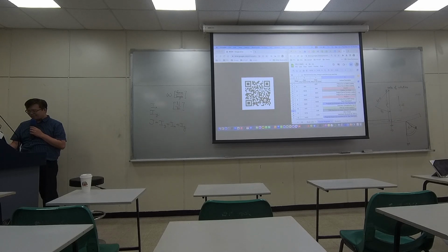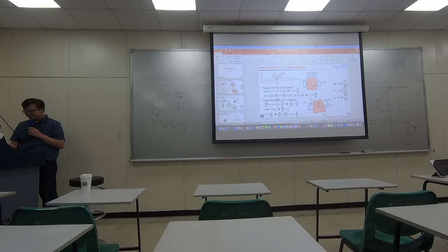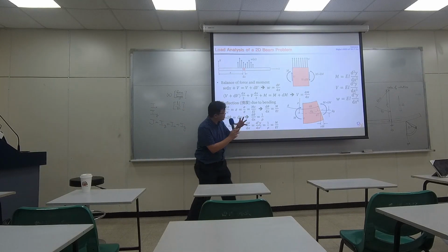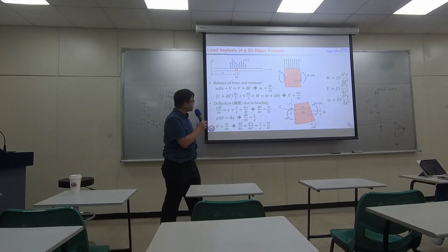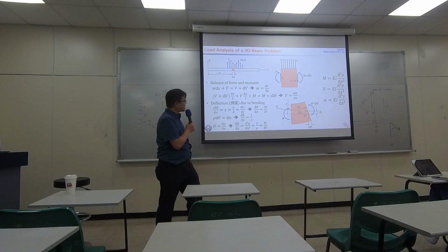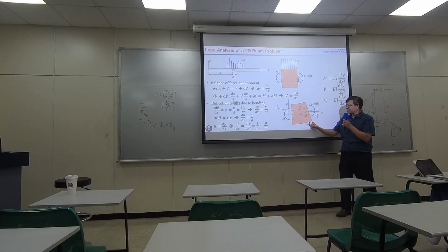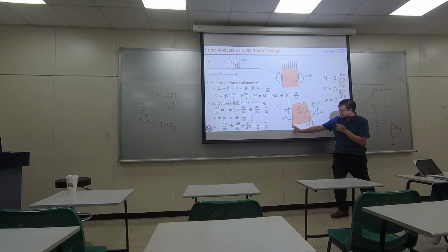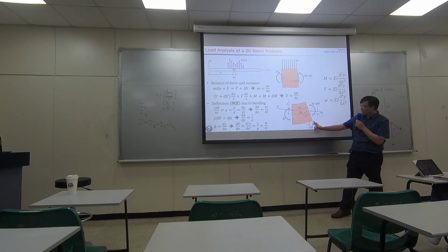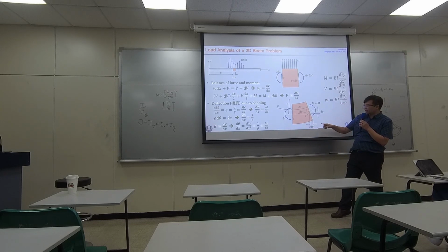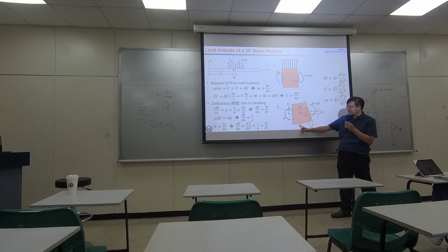So, back to our lecture. Now we know everything about that bending geometry. First, we will take a look at this particular area. Originally, the bottom edge has a length of dx. After bending, it was lengthened by this much. So how do we compute this?